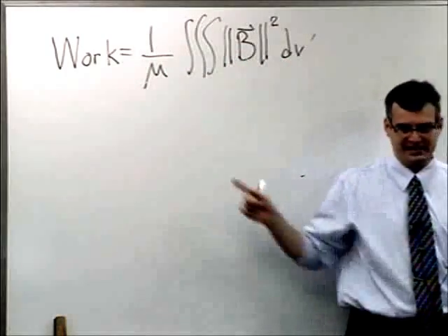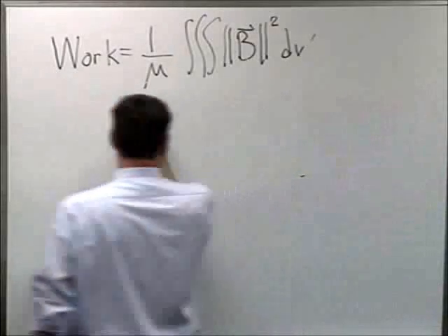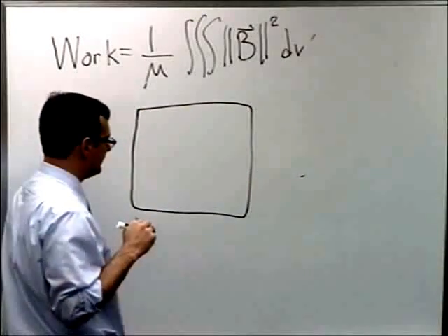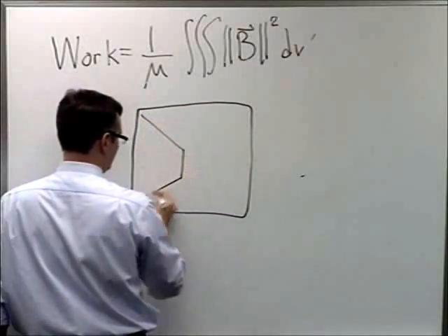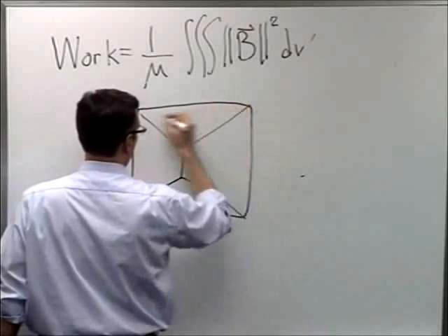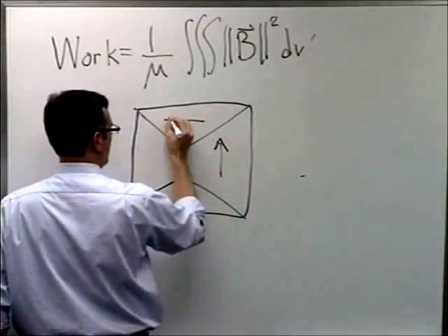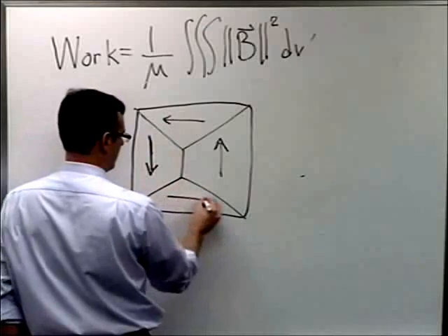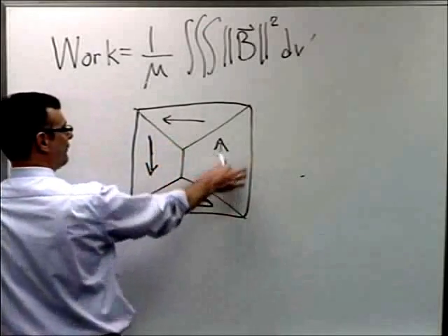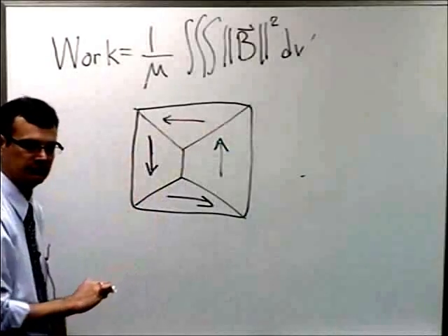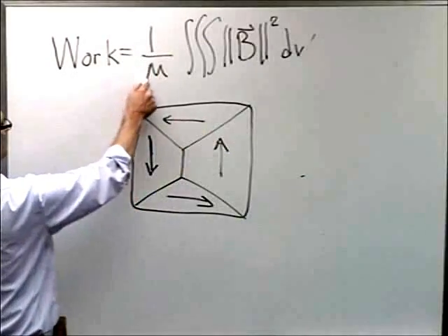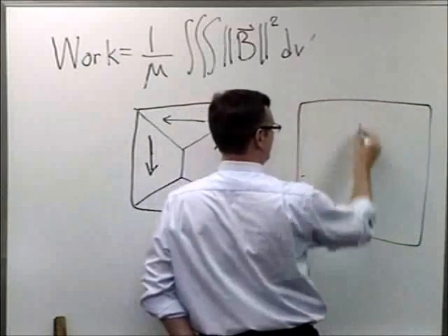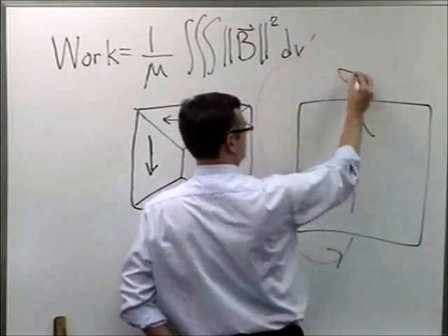Now, the process of domaining in these magnetic materials: let's say you have a piece of iron. It's actually a ferromagnet, but there are these regions inside called domains where they have individually permanent magnetic dipole moments, but they arrange themselves so that all the flux is circulating internal to the material. And in this way, you can keep the work of the system much lower than if this was one solid piece of cooperating material with an external return path for all the flux. Does that make sense?